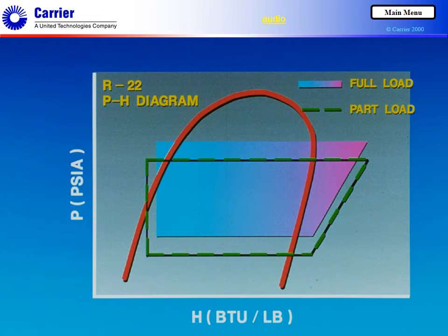A system using a capillary tube or fixed orifice metering device operates at maximum efficiency only at the design operating conditions for which that device was selected. These devices have no mechanical means for adjusting to load changes in the system. At all conditions other than design conditions, the system's efficiency is therefore not the best possible. Realistically, however, these devices operate just fine over a normal range of operating conditions. It is when loads change rapidly or widely, or when extremely low loads occur, that problems show up.